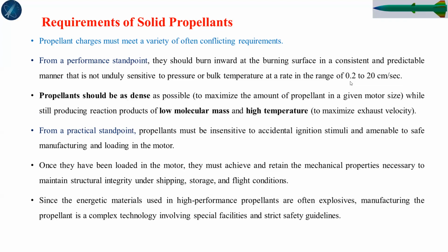Another requirement, from the point of practical aspect, is that the propellant must be insensitive to accidental ignition. If it is sensitive, then it can be ignited just in transportation, when we are moving it from place to place, it can easily catch fire and can cause damage to the whole design.